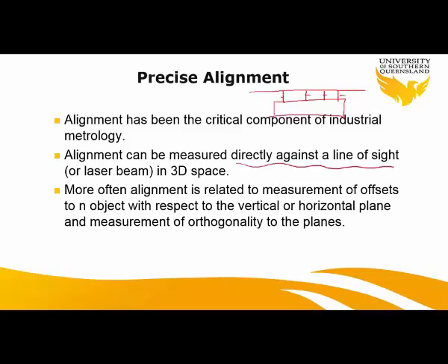But if you have a different surface, like if your surface looks like that, and then you're measuring the offset, my line is not quite straight, but if you measure this offset, some of them are higher and lower. So it means that your surface is not quite flat, so it can be used even for flatness and horizontality or verticality of the surface.